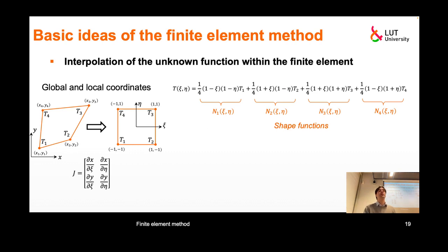So when you are dealing with finite element methods, basically you will always be talking about some shape functions. Shape functions describe which interpolation of the unknown quantity you assume inside each of your finite elements. It's clear that since we are assuming that something changes in a certain way, in this case linearly, the smaller the dimensions of my finite elements, the closer it can be to reality.